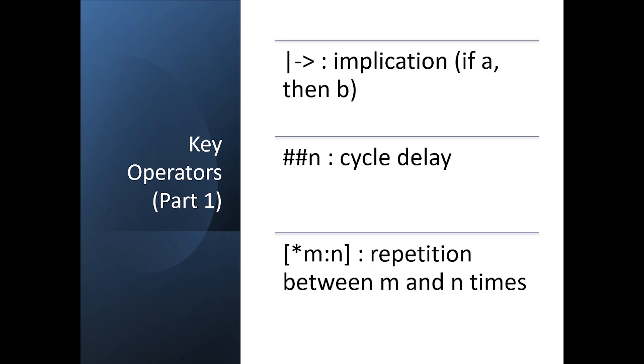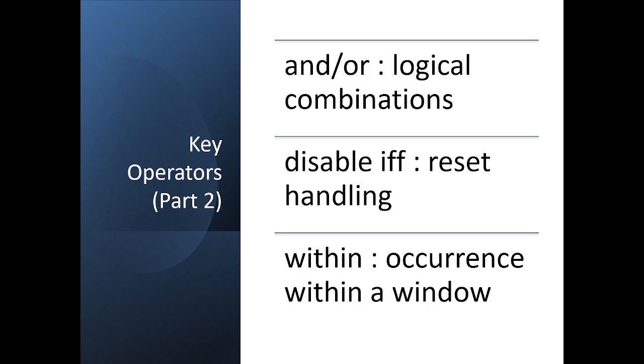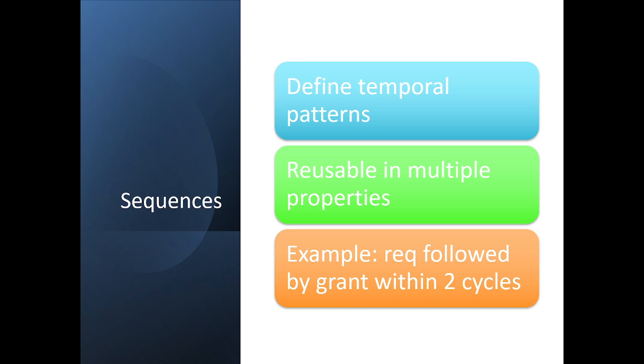There are also some operators for logical combination, disable iff for reset handling, and within to check occurrences within a window. These are the basics, and they increase the flexibility of writing code in SVA. That will be a great thing, the key operators.